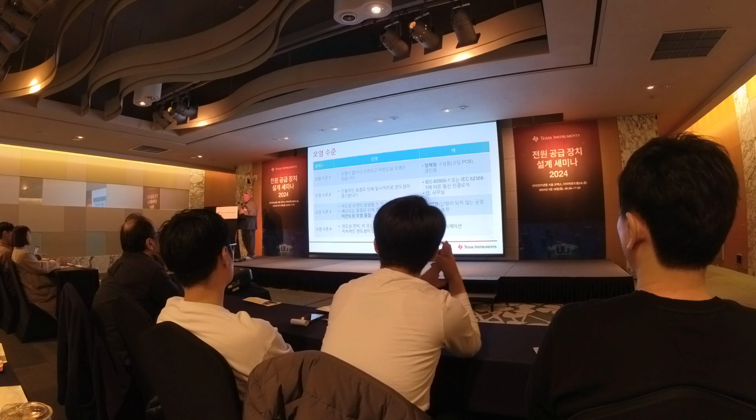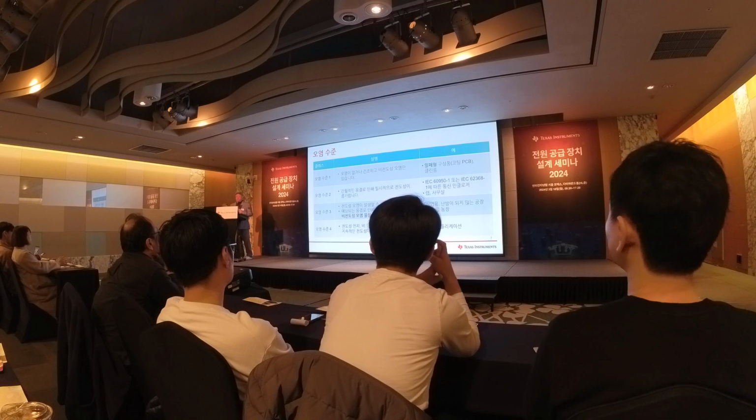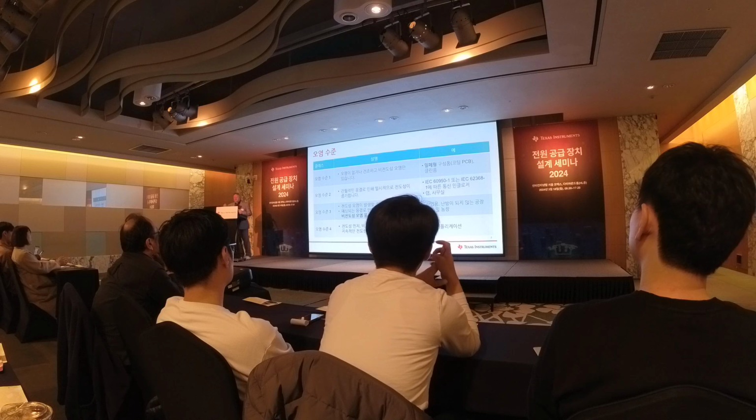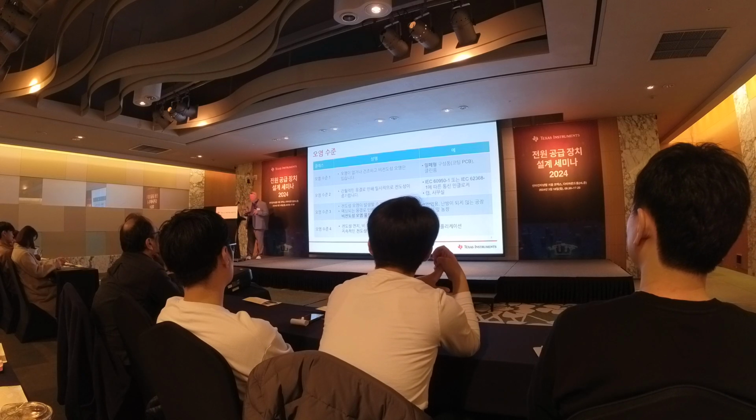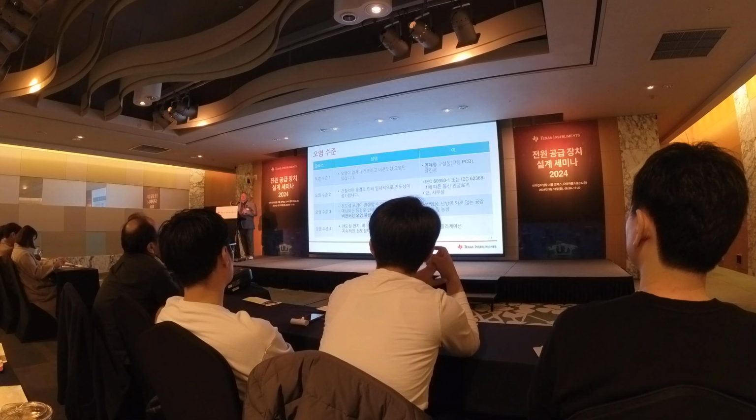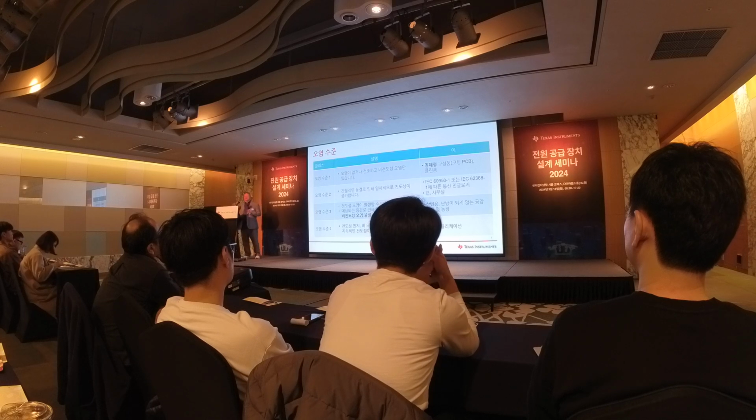So pollution degree 1 is the most strict. This is sealed components, inner layers inside of a PCB, anything that's inside of a clean room, anything that's inside of an environment where it is sterile or there is no moisture.